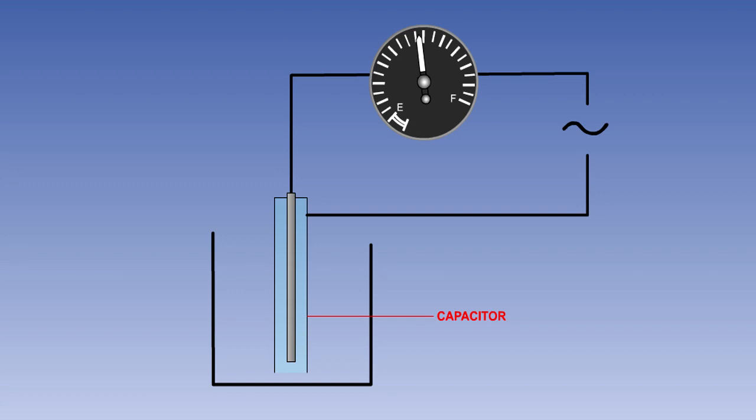Measuring the weight or mass of the fuel is done by having variable capacitors in the fuel tanks. The capacitive method works by supplying the two plates of a capacitor with alternating current. The current that flows in the circuit now depends on four factors: the level of the voltage applied, the frequency of the supply, the size of the plates, and the dielectric constant of the material separating the plates. In our circuit, three of these factors are fixed, and the fourth, the dielectric constant, is variable because the dielectric consists of fuel and air.